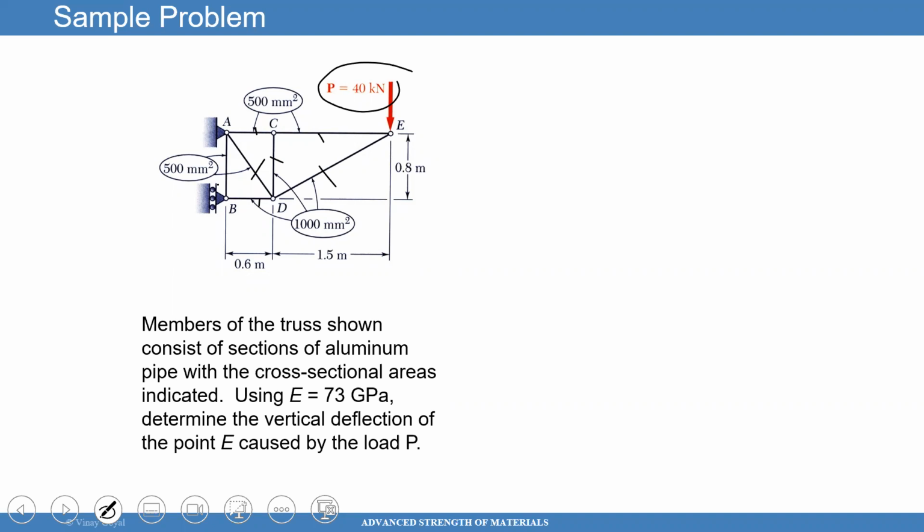Okay, find the load in each of these bars as a function of P. Can the energy be added? So I add the energy for all 7 bars. And what I'm going to equate that to? 1/2 P times the deflection Y, 20 points for you. And the way this works, you can add it to your homework when you submit it. That's one approach to make it easy for my TAs.